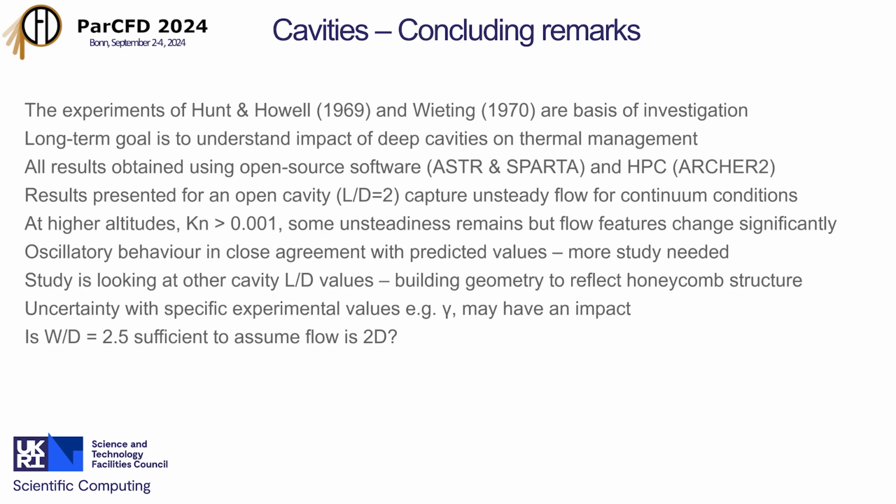Oscillatory behavior is in good agreement, particularly on the Strouhal number prediction for the continuum. And we now need to look at other effects of trying to reflect what was done with the honeycomb. Some uncertainty with experimental values, as I mentioned, and we'll have to look at whether the results with a width to depth ratio of 2.5 is really 2D. We might have to do the study computationally to see if there's any impact.